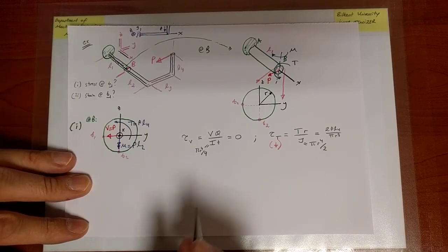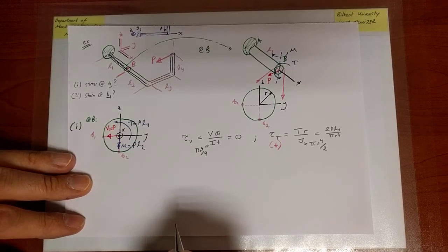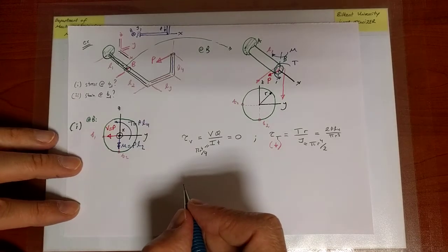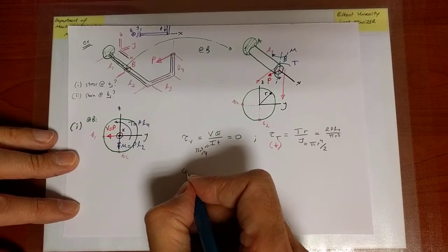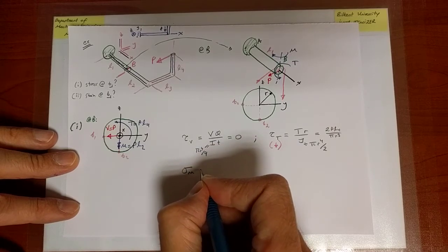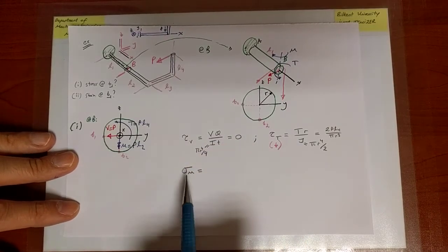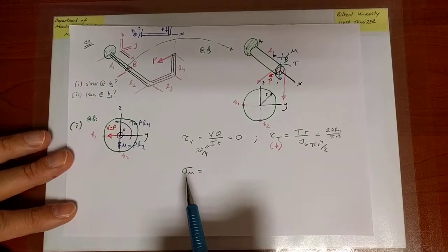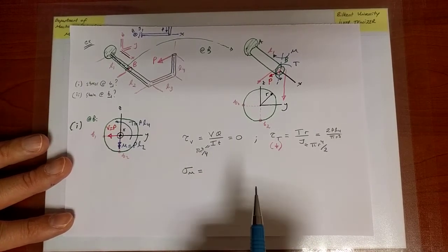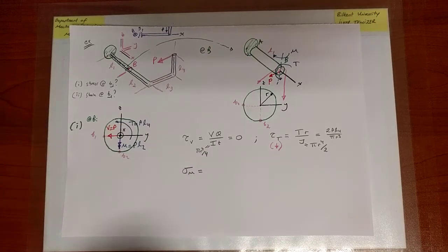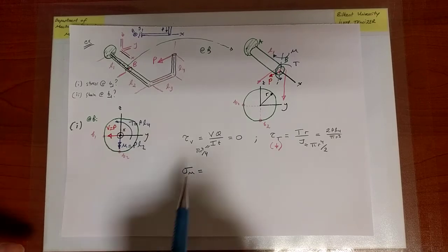So next we can look at the value of the normal stress. The normal stress is associated with the bending moment, so I'm just going to put here an M. I'm putting these subscripts so that we recall that this is just the magnitude of the normal stress, and it's not an X or a Y or a Z, because eventually the correct stress component, sigma X, Y, or Z, has to involve not only the magnitude but also the correct sign.